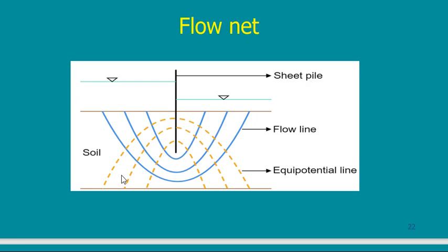So the first thing you should do is to start with the flow lines. Start by putting any flow line. I will put this one. And then I keep in mind that the next one should carry the same amount of water. Usually they tell me something, keep in mind, take this distance. This is the narrow area. This is the thickness of the first flow channel.